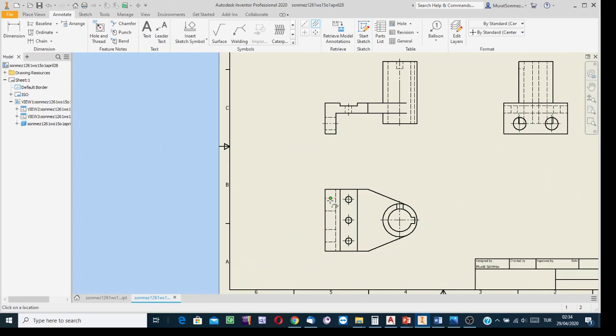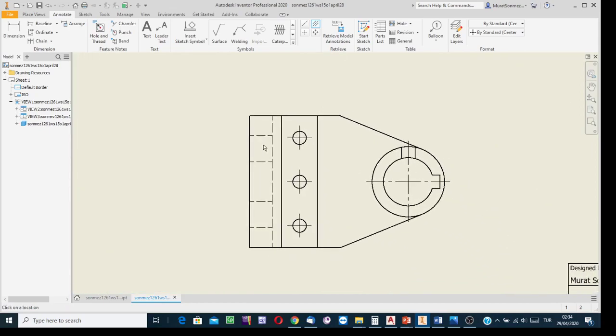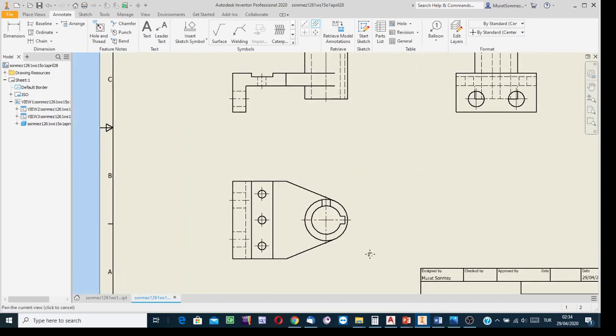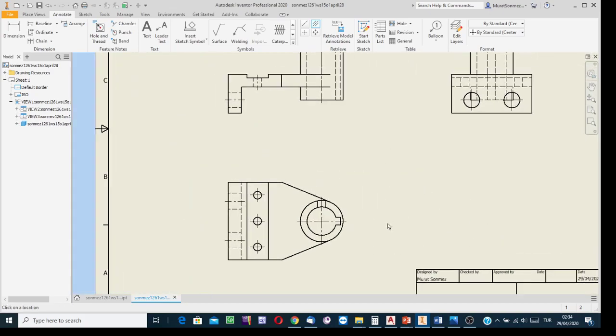Okay, on the top view, this hidden rectangle corresponds to the lateral side view, the top view of the holes. Their dimension is 12. Okay, indicate the longitudinal axis. You know, the axis is to highlight that such a part on the projection, a rectangle, is not the image of a rectangular prism. It is to say that the image of a revolved feature shows the longitudinal axis. At the view reading stage, it is quite meaningful. If there is an axis, then this means it's a revolved feature.